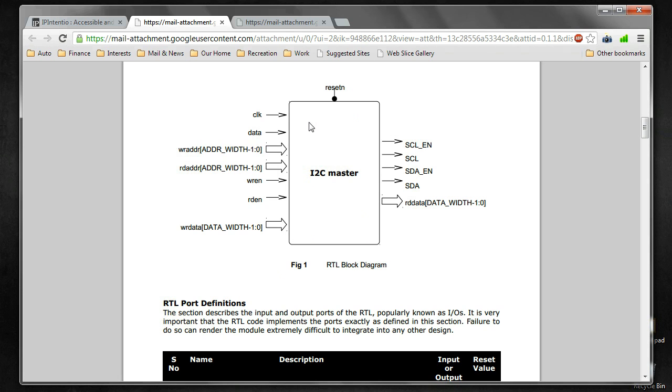So based on this, you also need to make your functional driver, which will have the exact opposite inputs and outputs of the RTL. Of course, the clock and reset will be inputs to all components except for the clock and reset generators. All your components need to be encapsulated in a test bench which does not have any inputs or outputs.